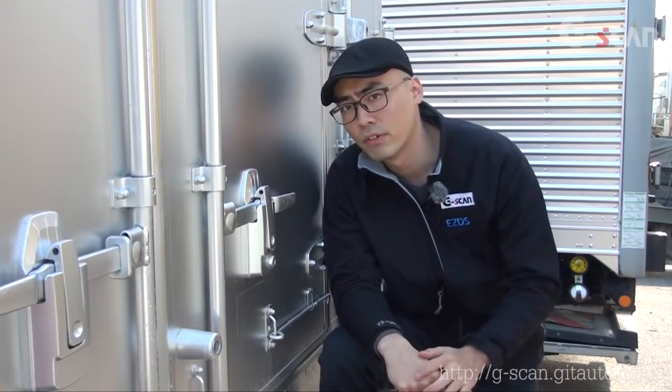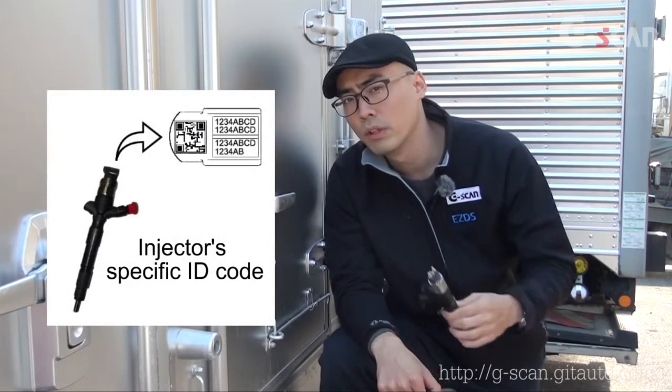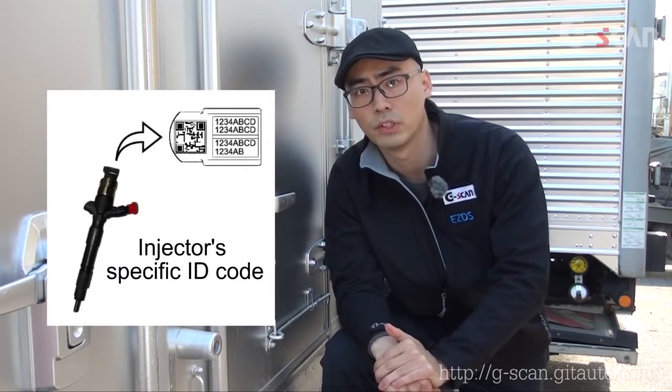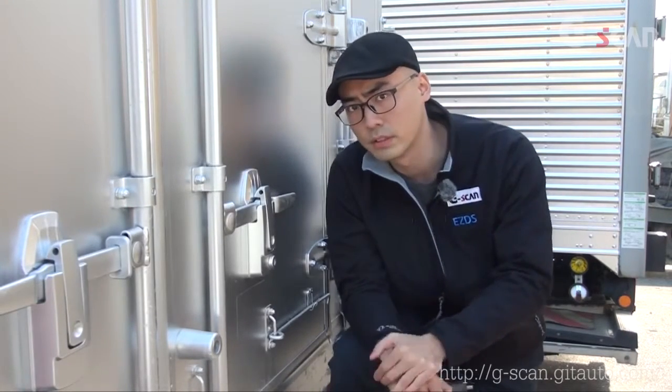One out of many different examples would be injectors. When you replace injectors, you have to code or write the specific injector's ID code into the ECU for correct fuel quantity adjustment. Let me summarize some key points.